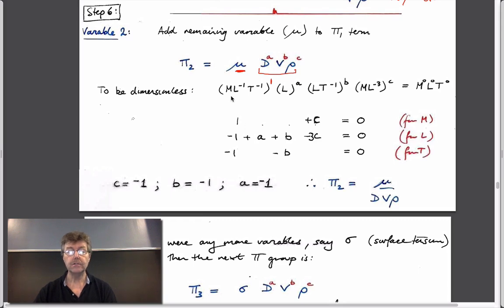And so viscosity, if we go for mass, viscosity is to the power 1. And this is the same as before. If we look at length, then this is to the power -1, which is this term here. And these 3 terms are exactly the same as before. And then for time, time is to the -1. And these other terms are exactly the same as before.